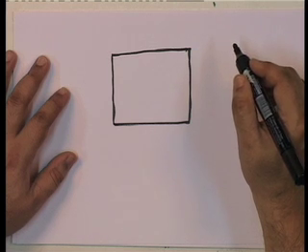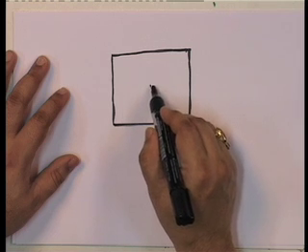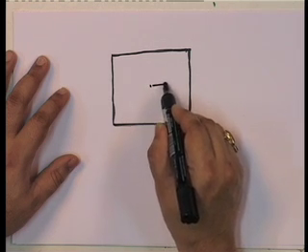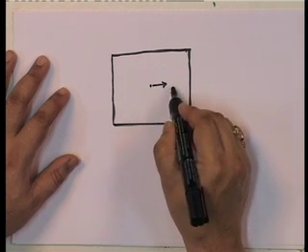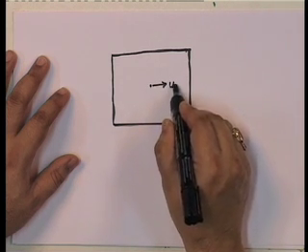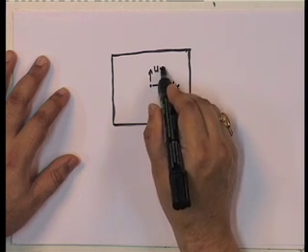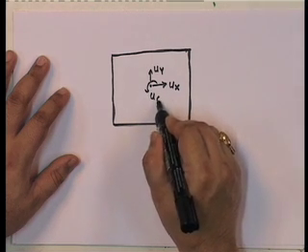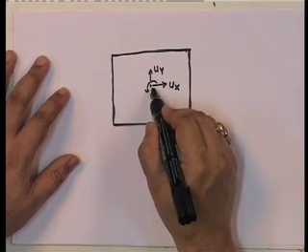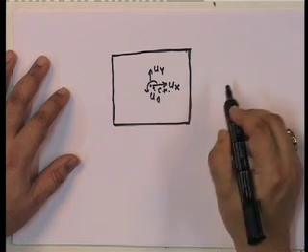So, once you have rigidity in plane, you can actually define the degrees of freedom in this fashion at any point. Typically what we do is we consider u x, u y and u theta, defined at the center of mass.